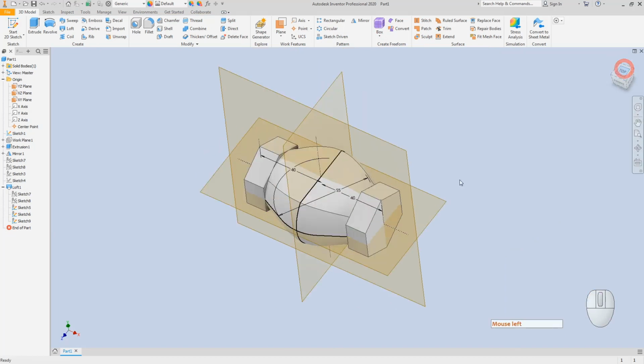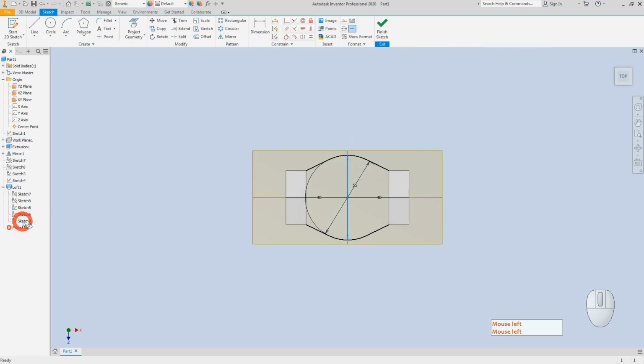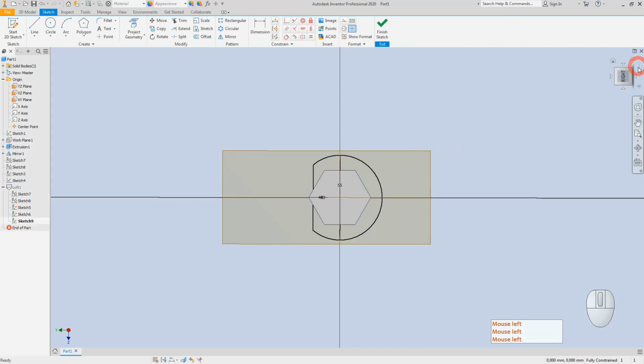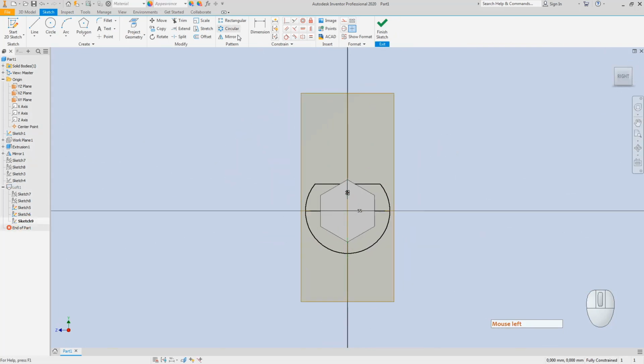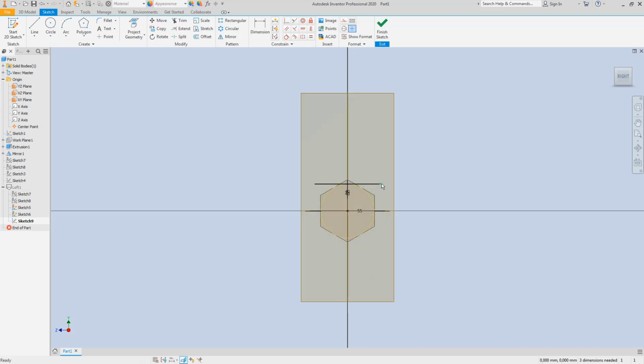As you see, this time I have just corrected, but the dimension is not true. For this reason, I'm just going to correct the profile. This time it is not on this one. I will erase this profile, this arc shape profile. Let's keep the other side first, then create a new line to sketch on and convert this line for construction purposes. I will again enlarge these two lines.